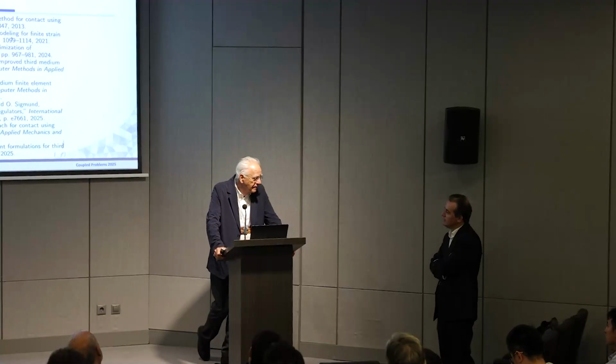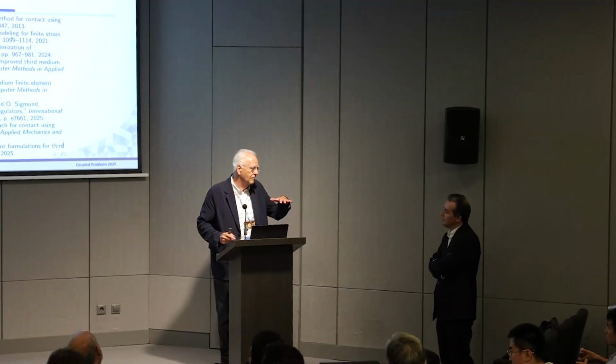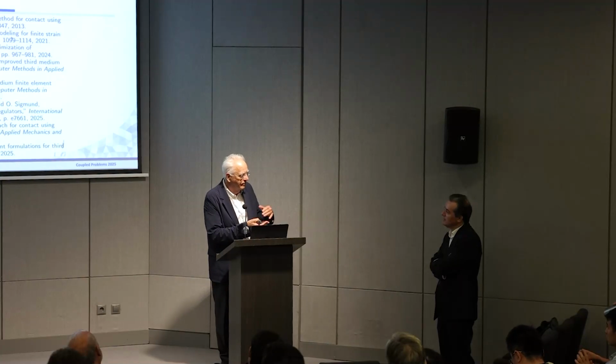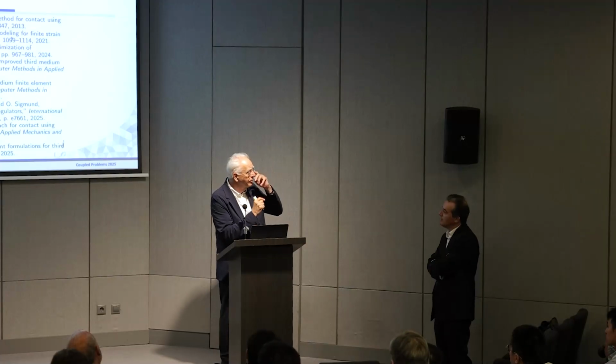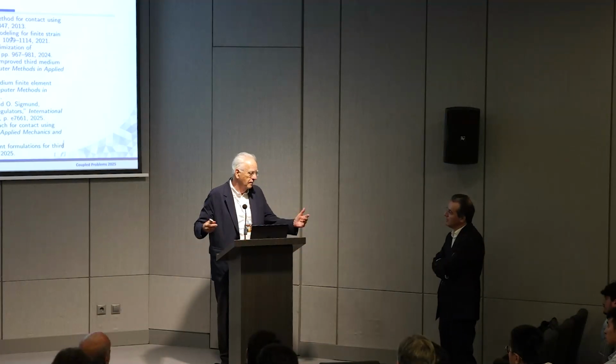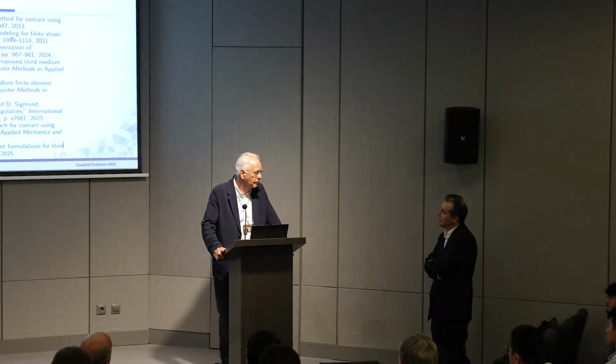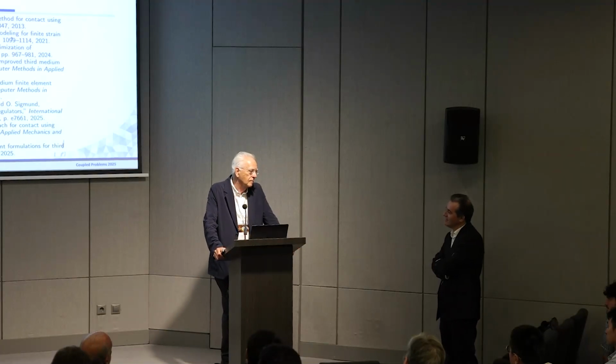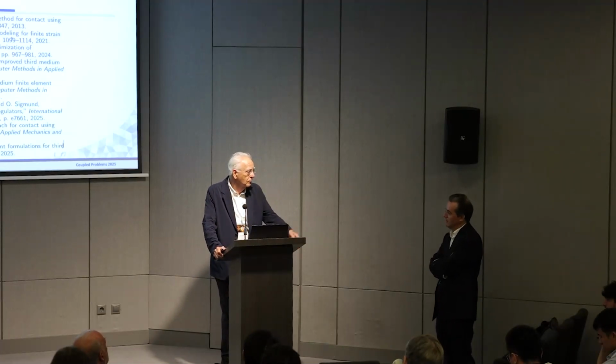But the other thing is that I think the third medium here acts only as a sort of property. So you get the gas conductivity with the third medium, which is automatic. And if you get closer and closer, you get the spot conductance, which is the conductance of the solids. So actually you can monitor what people thought about this with very complex models. You can find some analytical models about this in the literature, very old ones. We have worked with Giorgio Savarese on this topic some years ago, but this can be done. But here it's automatic.